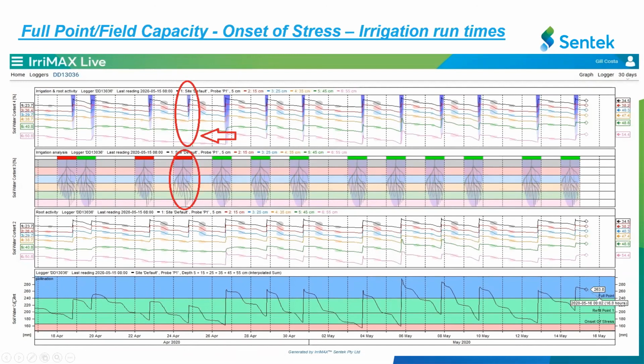And I'd like to emphasize the bottom graph where you have the blue and the onset of stress. The line between green and blue, that's where my field capacity would be. And my onset of stress would be the math we did. This happens to be a field that has plums. So I grow black plums, and I have a maximum allowed depletion of 40%. And then every spike is an irrigation event, right? So I can let the water dry out, or the plant evapotranspirate this water as it uptakes carbon, and then I'll irrigate again and again throughout the season.